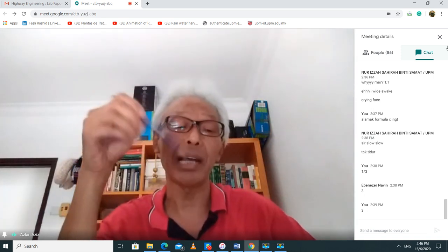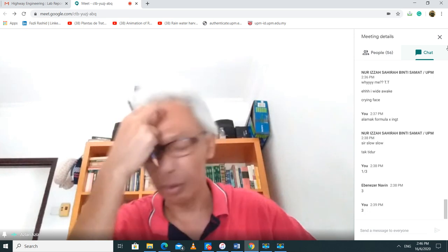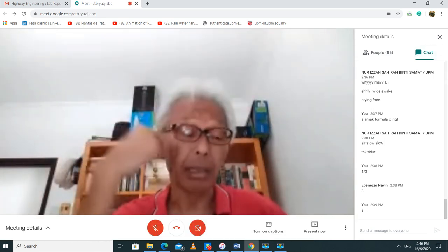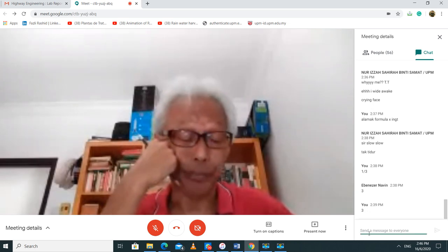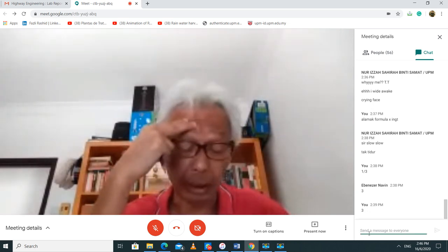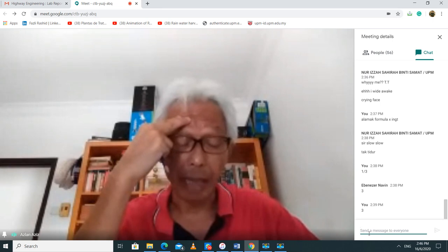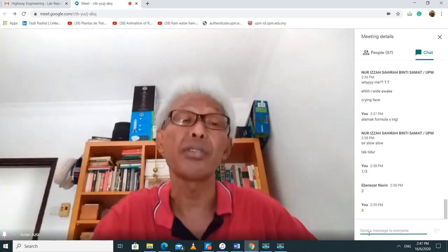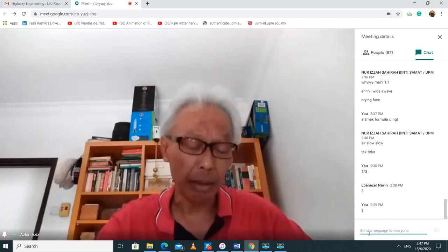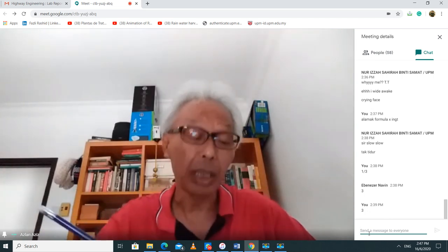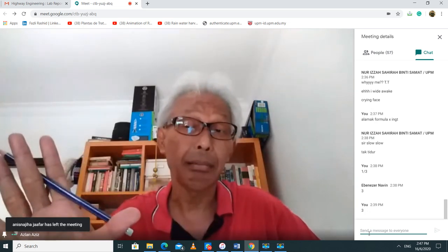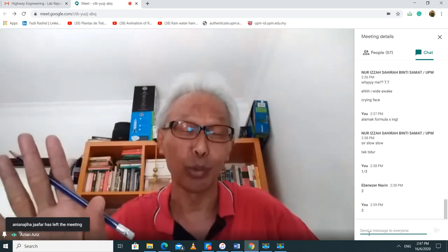And if I say that sigma 3 is related to sigma 1 by some coefficient, I have said to you earlier that this is the at rest condition. So I have sigma 3 over sigma 1 is equal to K0. So sigma 3 is equal to K0 multiplied by sigma V. Are we okay? Or am I losing you?